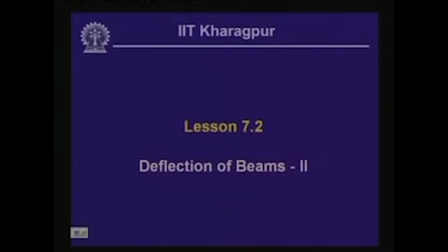Welcome to the second lesson of the 7th module, which is on deflection of beams part 2. In the last lesson, we introduced the concept of deflection of beams, and how deflection of beams plays an important role in engineering structures. We derived the differential equation for the elastic curve, and subsequently the equation for the elastic curve, and we saw how to compute the deflection of a beam at any point for a